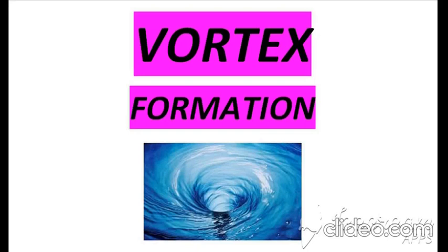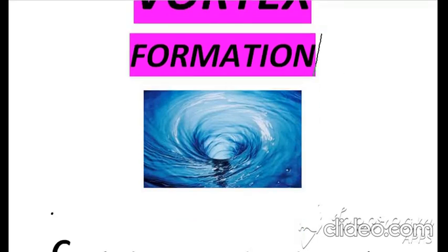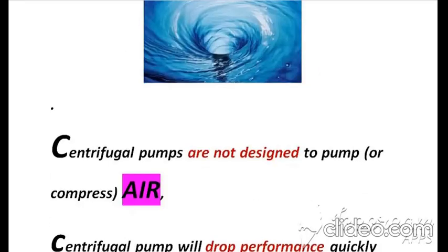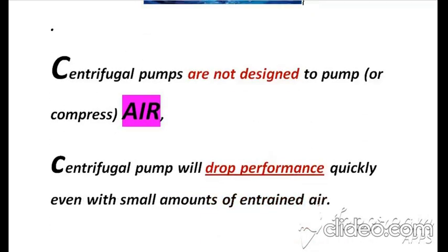During development of the net positive suction head concept, it's important to know about vortex formation, which is also a problem created during pumping if net positive suction head is insufficient. You can see the vortex picture, and during a vortex, air is ingested into the pump body, and centrifugal pumps are not designed to pump compressed air.